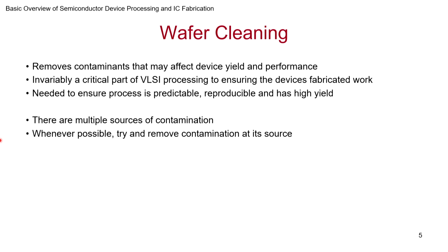It's like cleaning a room. If you want to clean a room, you want to make sure that you keep the room from getting dirty as much as possible. It's not that you put dirt and then clean. That won't help. And sometimes we may not be able to clean it perfectly, and so some dirt will remain. Same with wafers. So if you allow contaminants to come, we think we are cleaning it, but who knows, we may not be cleaning it perfectly. So it's a good idea to make sure we avoid contamination at the source, but there is a limit on how much we can do, but we try our best.